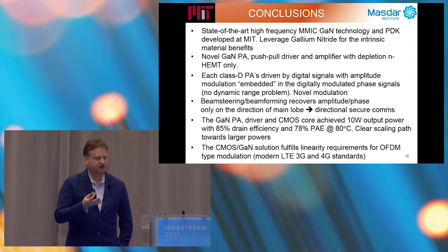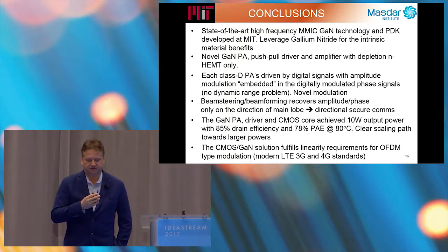The gallium nitride PA driver and the CMOS achieved 10 watt with 85% drain efficiency and 78% power added efficiency. And last but not least, the CMOS gallium nitride solution fulfills the linearity specs for OFDM 4G standards.